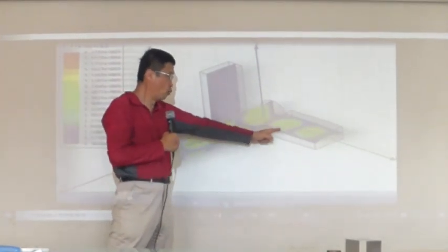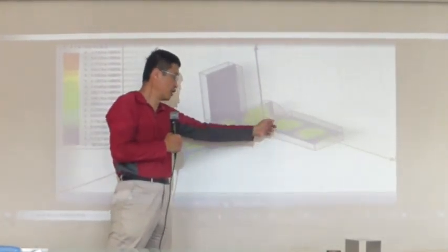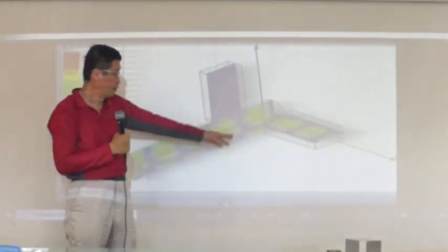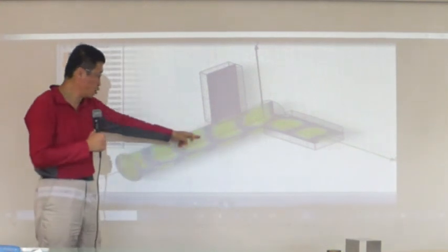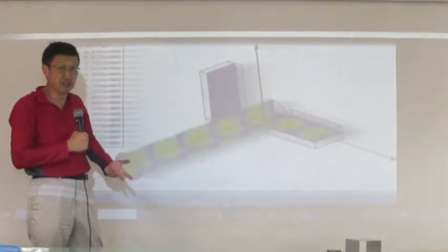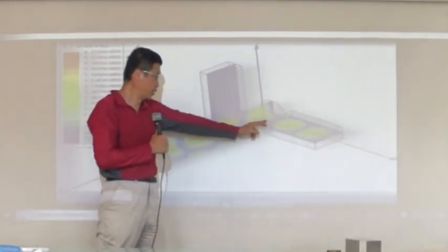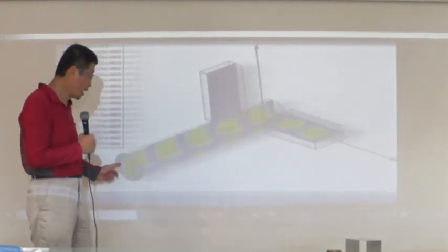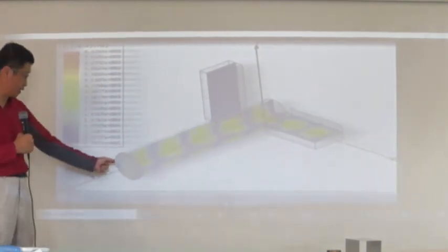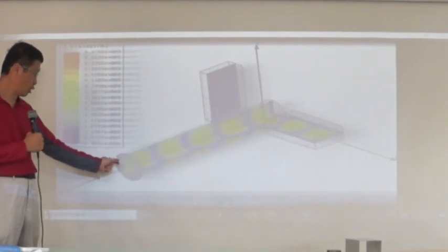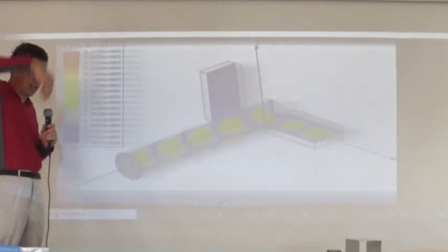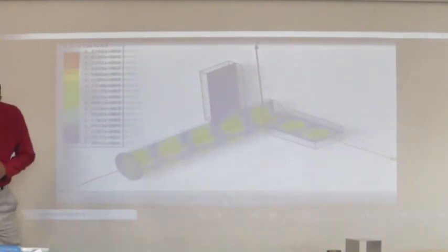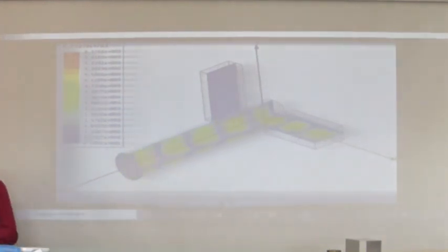Some of the wave will be transmitted and part will be reflected back. But at least most of the energy will be converted from the rectangular waveguide to the cylindrical waveguide. Okay? So the polarization is linear. It becomes large, small, large, small. Actually, it's linearly polarized. That's the linearly polarized wave. Okay? Let me show you another one.